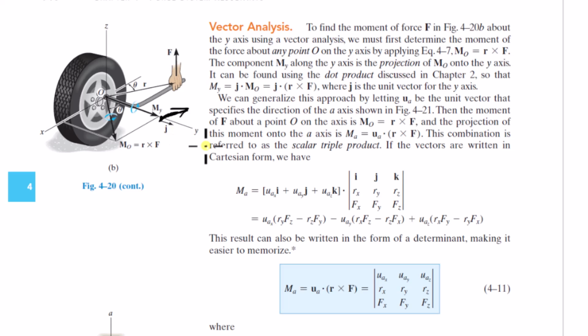So if you slide that moment vector on that axis anywhere, you're not changing the force, right? To slide that vector, you don't have to change the whole force system. If you found the moment of this force about this point, and here's the result, well, now you can't just go sliding this vector without changing the whole force system. I know it's really confusing. It depends on the question you're asking. If you found r cross f and got this vector here, that's the moment of f about O.